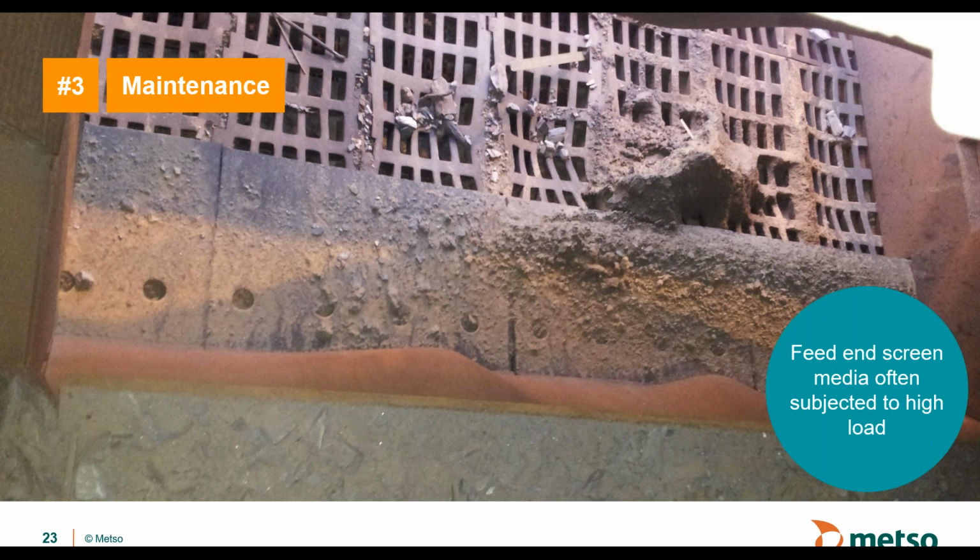If the feed had been dropped on the feed box as intended, that lining is much stronger, can take a higher impact, and can handle the load better. The screen cloths are more sensitive in that sense, and that's why you see some bending here. The lifetime of the installation will then be shorter, for the exact same reasons we discussed on the previous page.